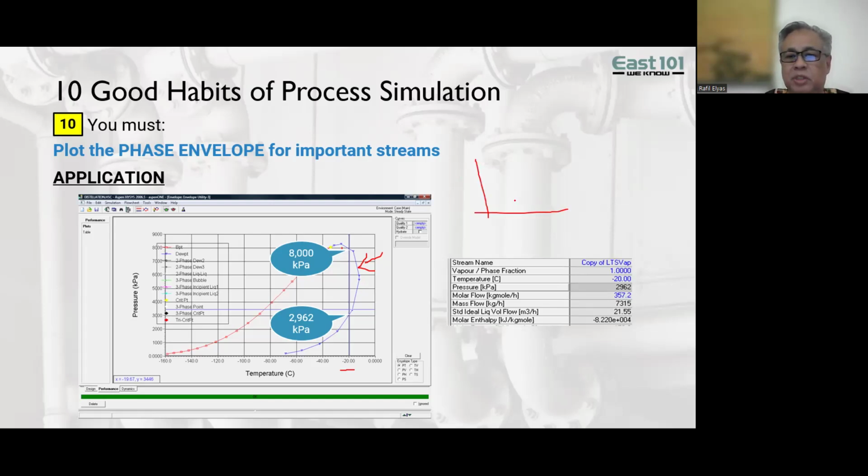Normally, if you have leaner compositions, you would expect to see a thinner phase envelope. So if you use HYSYS and punch in minus 20, you'll only get 1 point, but you'll only see this retrograde dew point if you plot your phase envelope. There's actually a numerical trick in HYSYS. If you put -1 instead of 1, you will get the retrograde dew point of about 80 bar. So that's like a little trick. But I don't think it's documented anywhere.